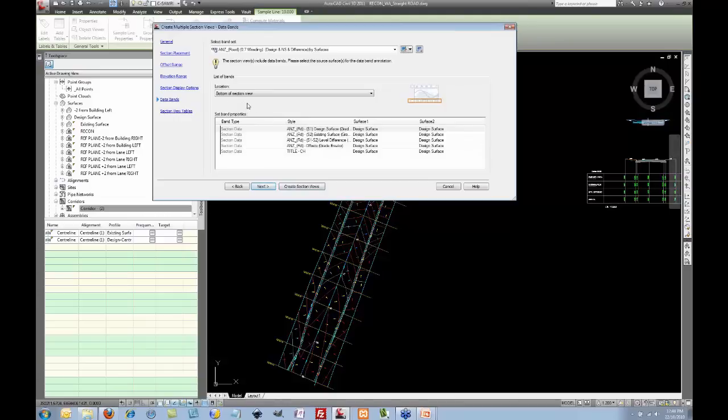Last step is the bands themselves. So you still have to go and do this irritating step where you tell the software which surface corresponds to which area. So S1 is design and S2 is existing, which you see from where the mouse is hovering now. So on S2, you go to existing. What I do here is double click and press E for the first letter, just to save a few irritations.